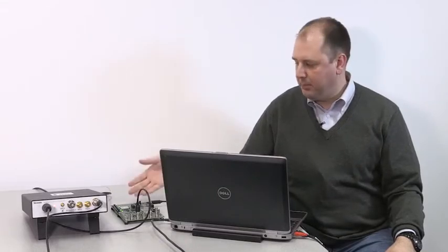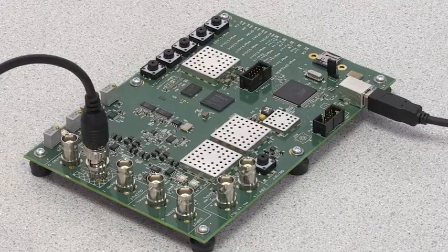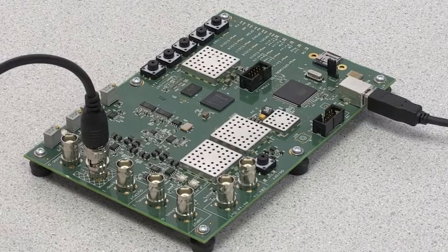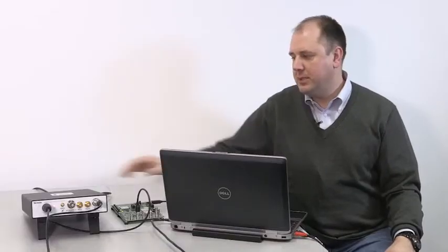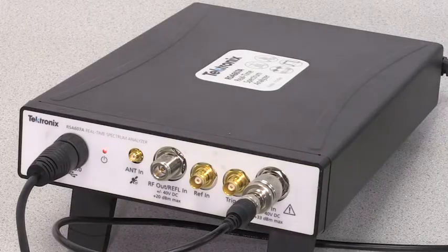And I'd like to show you a quick how-to video for doing Bluetooth pre-compliance checks on a Bluetooth device. In this case, I've got a demo board here available, and I'm going to do the test with this RSA607A real-time spectrum analyzer. It's a USB analyzer that's connected to my PC. The PC will be running SignalView PC software to control the analyzer.